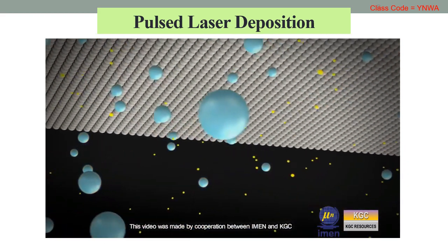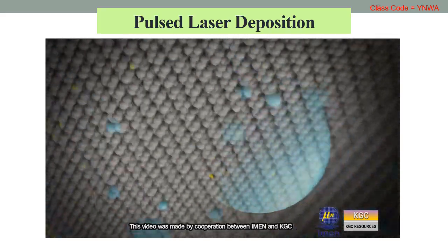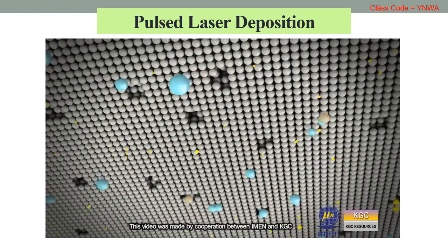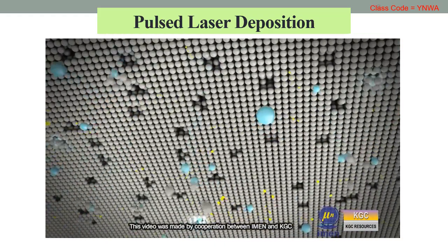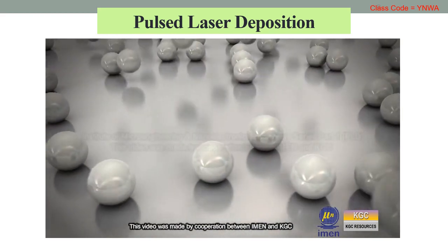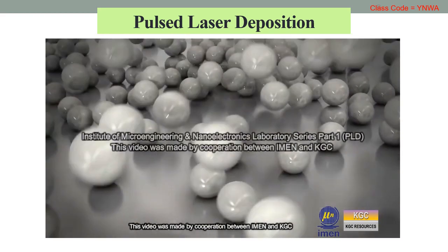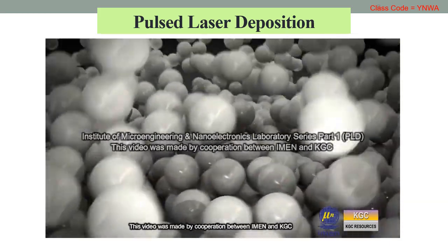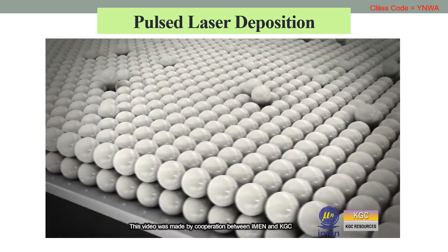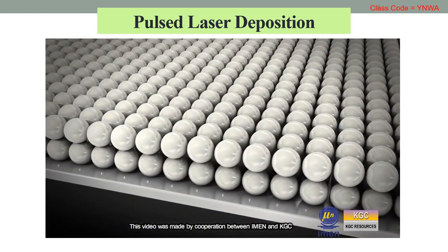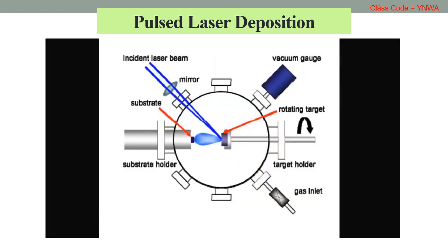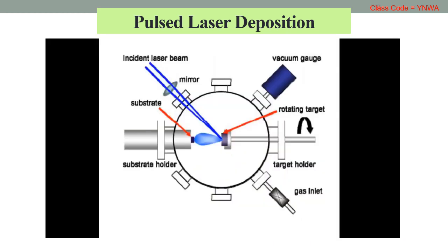When the laser pulse is absorbed by the target, energy is first converted to electronic excitation and then into thermal, chemical, and mechanical energy, resulting in evaporation, ablation, plasma formation, and even exfoliation. The ejected species expand into the surrounding vacuum in the form of a plume containing many energetic species, including atoms, molecules, electrons, ion clusters, particulates, and molten globules before depositing on the typically hot substrate.